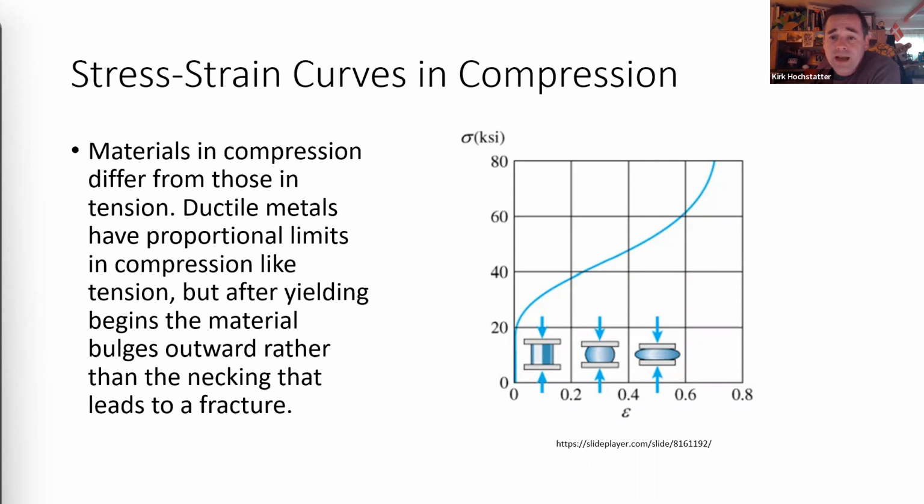When the material is compressed, it bulges outward on the sides and becomes barrel-shaped because friction between the specimen and the end plates prevents lateral expansion. With increasing load, the specimen is flattened out and offers greatly increased resistance to further shortening.